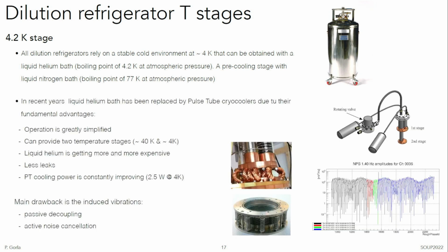In more recent years, the liquid helium bath was basically replaced by this kind of cold head, what people call pulse tubes. These are cryocoolers which have a closed thermal cycle performed with gaseous helium with a thermal expansion.